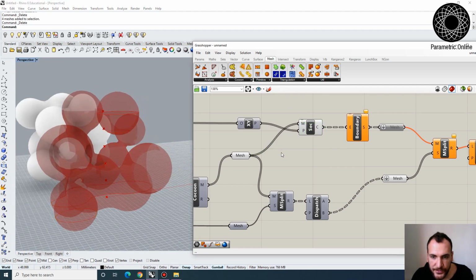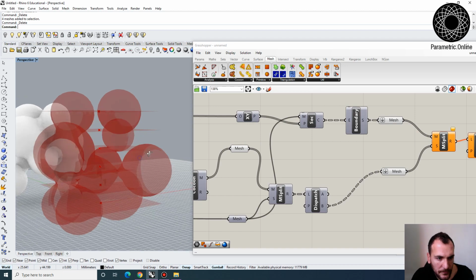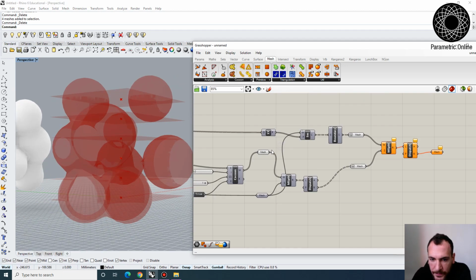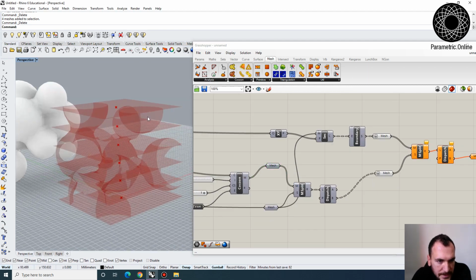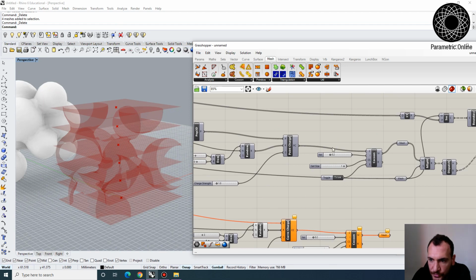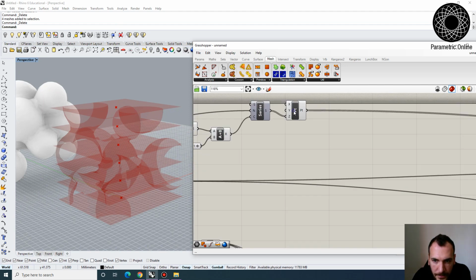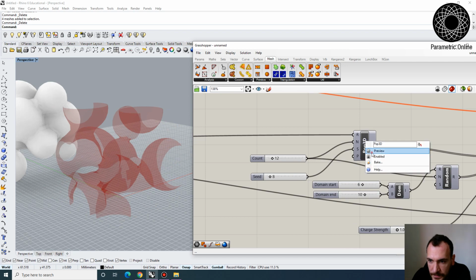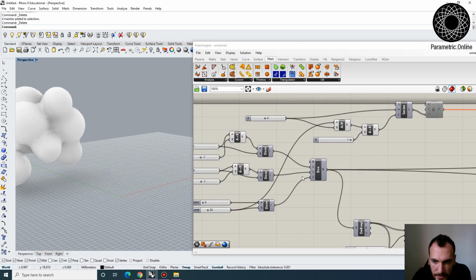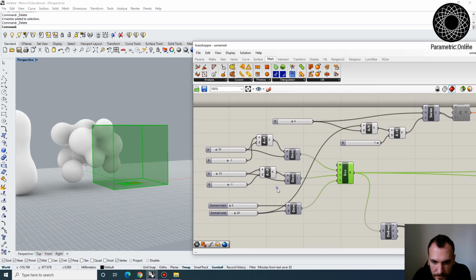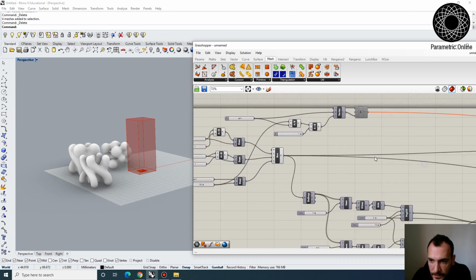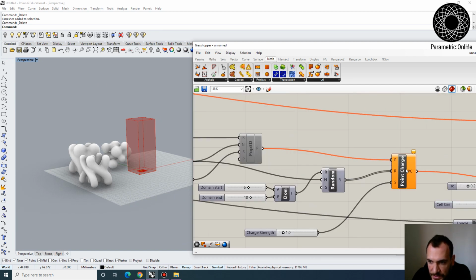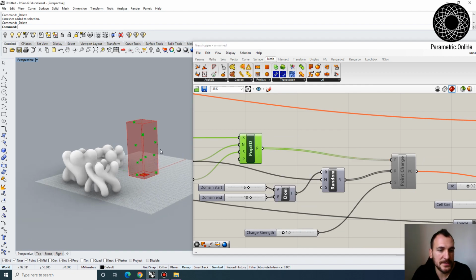So maybe go back to the older version. So that's it. And let's go back and let's see. Let's play around with the parameters a bit. So I'm going to disconnect this part and disconnect this part. Then what I want to do is look at the initial box, make it a bit more vertical. So increase the height, maybe make it like 50. Then let's look at our population before the point charges. So these are where the points are going to be sampled.